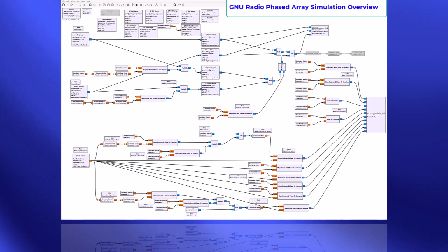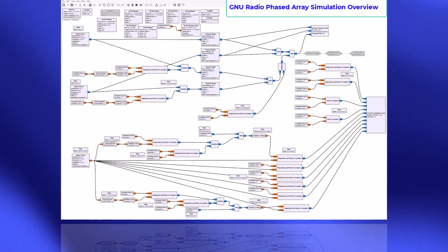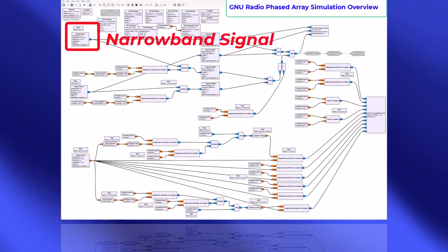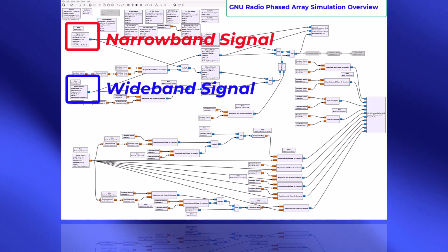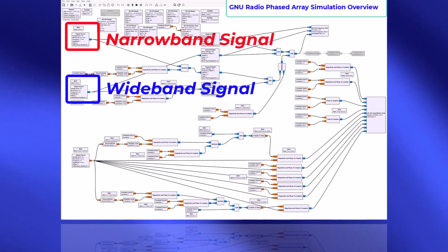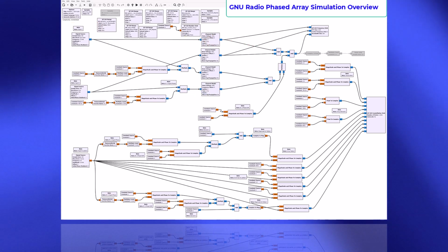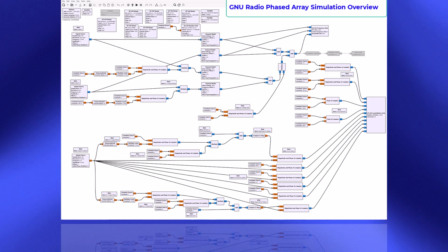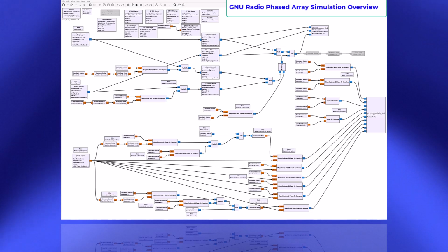The simulation uses two signals, and so we have a signal source here, another signal source here. We have two elements in our antenna array originally, so this will be a phased array but with just two elements, and for convenience we selected one of those elements as a reference and the relative phase of the two signals, regardless of their angle of arrival, as a reference, and we'll just call that 0.